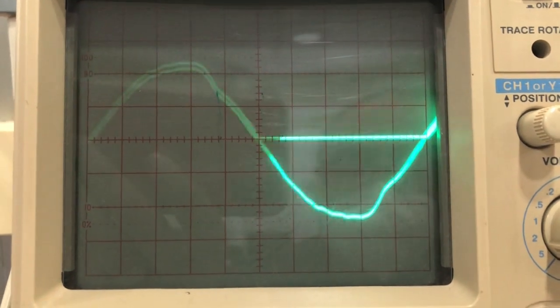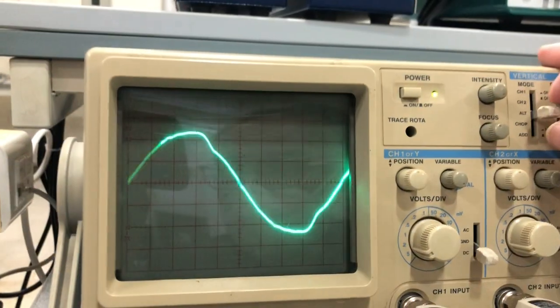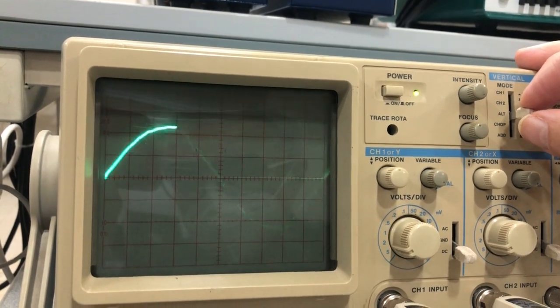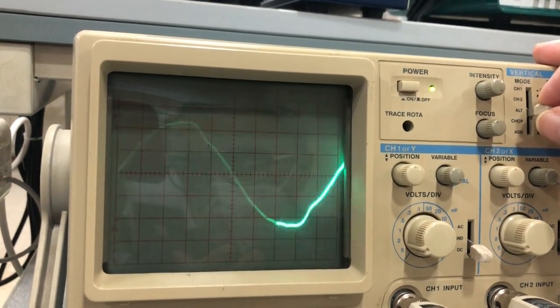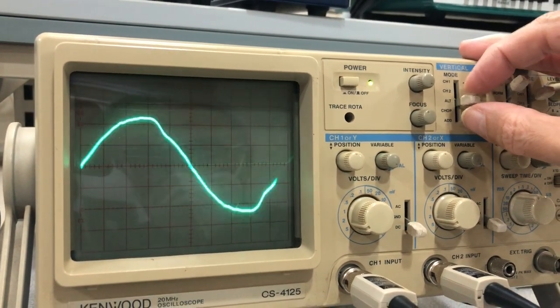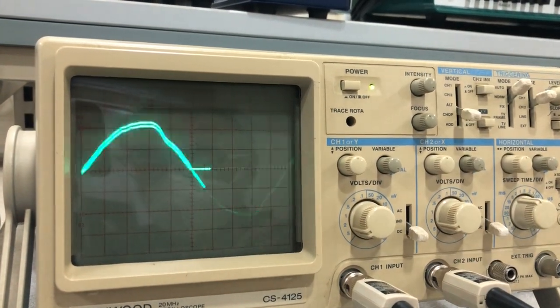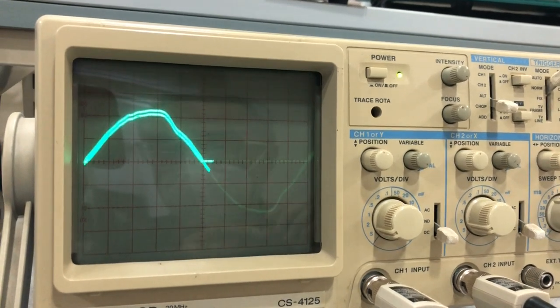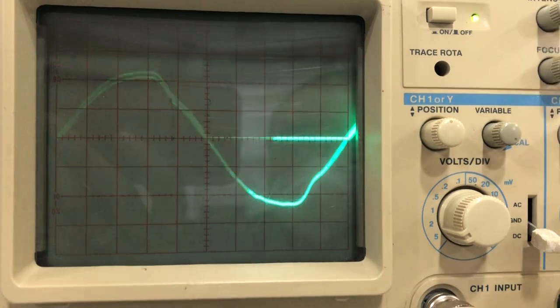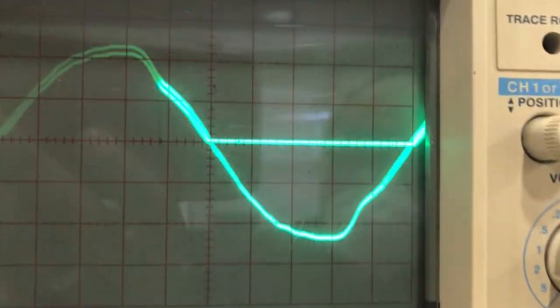Let's go to chopping. You see, alternating is flickering because it plots one and it finishes it and then it starts plotting the second. That's why you see them rippling, because the curve has to be plotted after the first one is finished. But when I plot it in chops, in small pieces, then they look less flickering. But at high frequencies that may not be the case, okay?